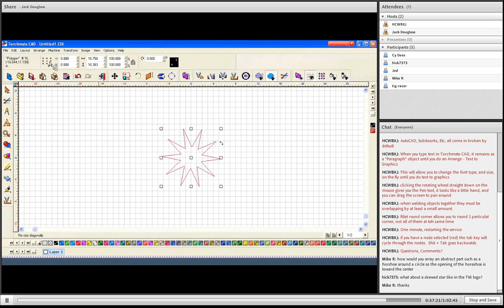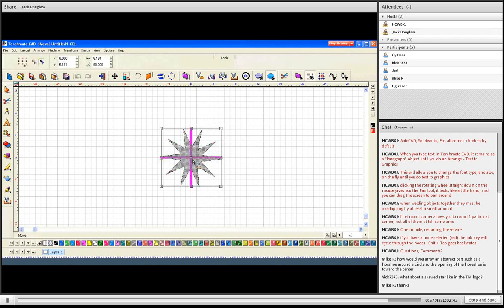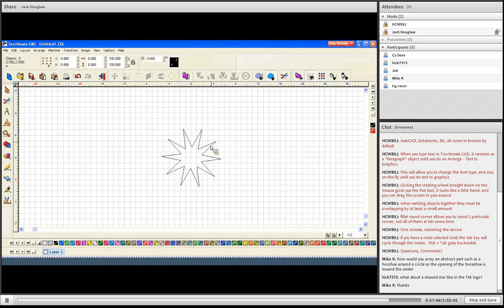and so if I select the center one and turn it red, I'm setting the coordinate for the center. If I choose the right middle one, I'm setting the coordinate for here. Top right, this coordinate, and you can see as I select these, they change. So clicking on the center box gives me the coordinates for the center, and I know that I'm centered at, in this case, the origin, or 0, 0 on the ruler. When I say origin, that's what I'm referring to.